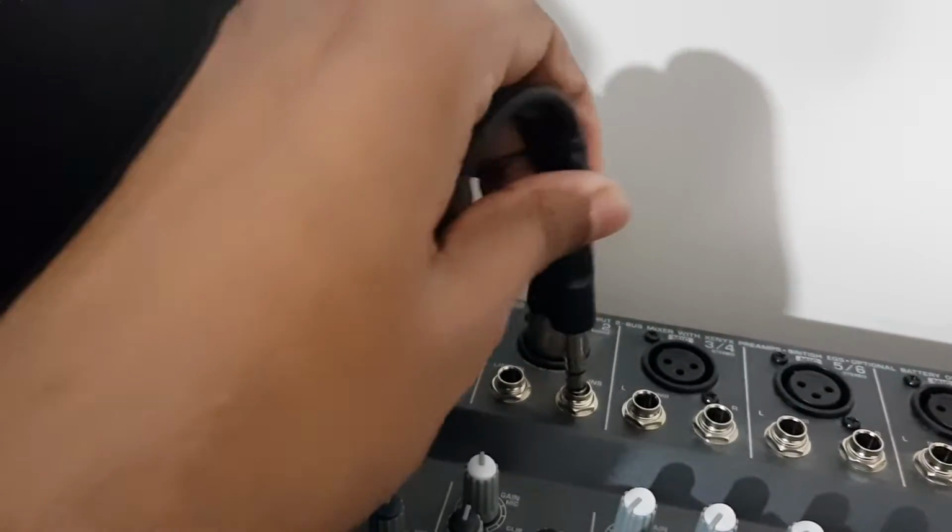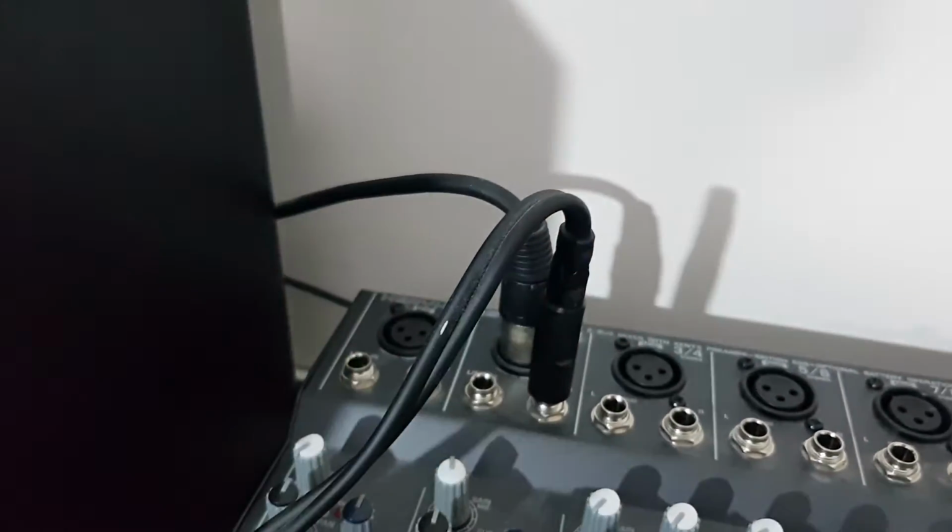Insert cables are usually labeled, but I'll explain which side they plug into. The one that's on its own is the insert cable, and that goes in your insert port on your mixer. And these two, which are usually labeled, tell you which is the tip and the ring, and they go into the back of your compressor. It's really simple, just follow the markings on the back of your compressor and match them up with the labels on the cables.